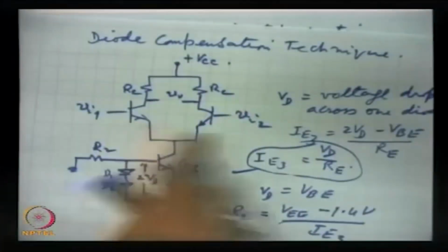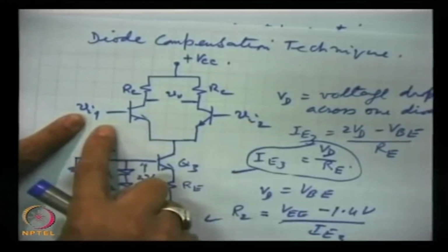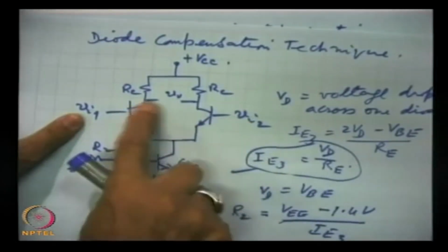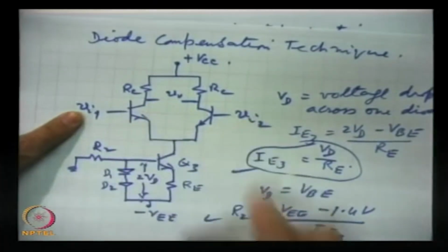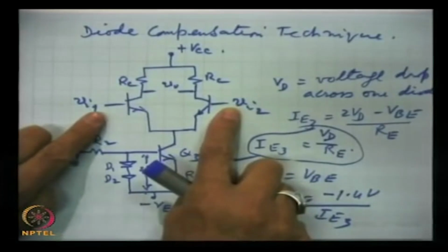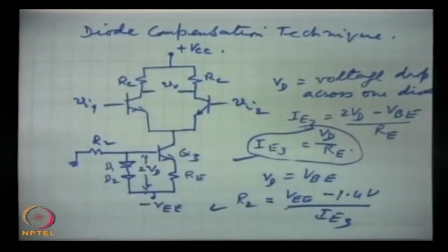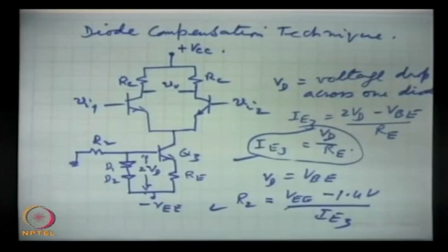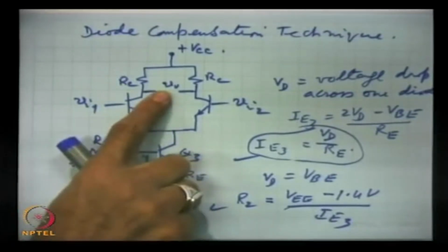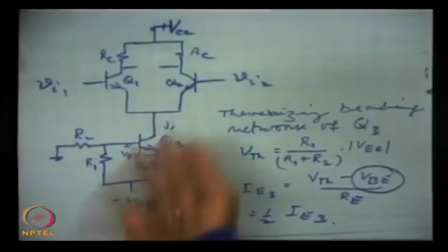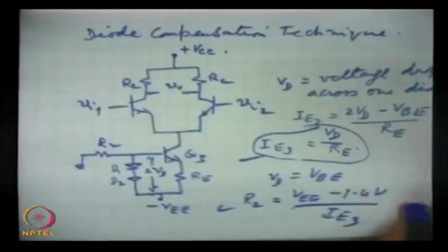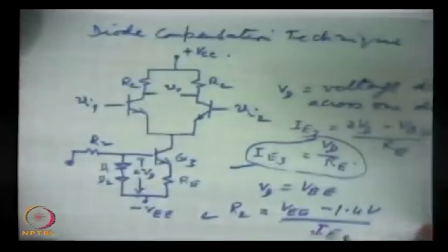In any circuit we take, in the differential mode, when we take the output from the two collectors, whatever signal is common to both is totally rejected, it is absent in the output. So, whether this circuit or this circuit, that does not make a difference. Now, this is an ideal situation.